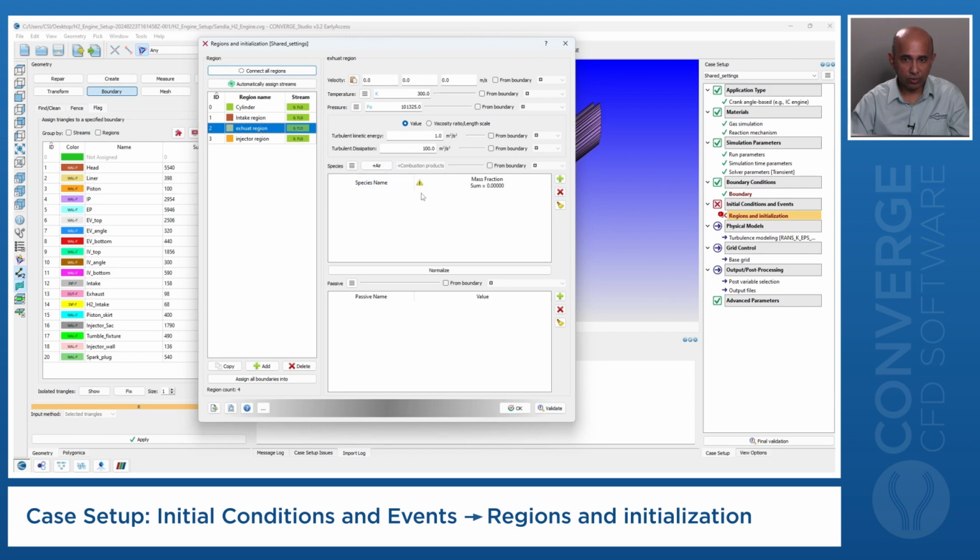And exhaust, again, it's going to be from your exhaust products. Now this is at high temperature, so it's at 800. The temperature is after the exhaust stroke, right? So this is low now, 275.1 from my data sheet. This is combustion product, so water and oxygen and nitrogen.